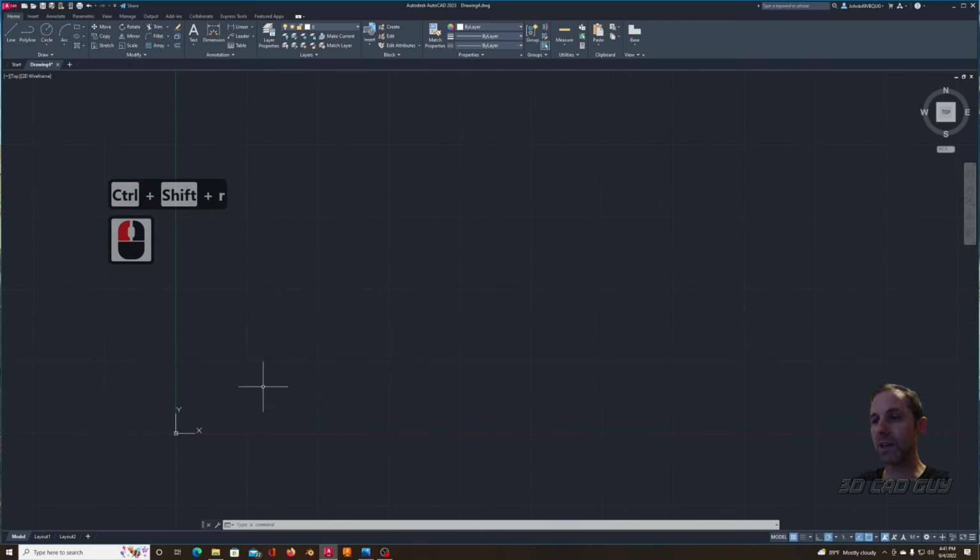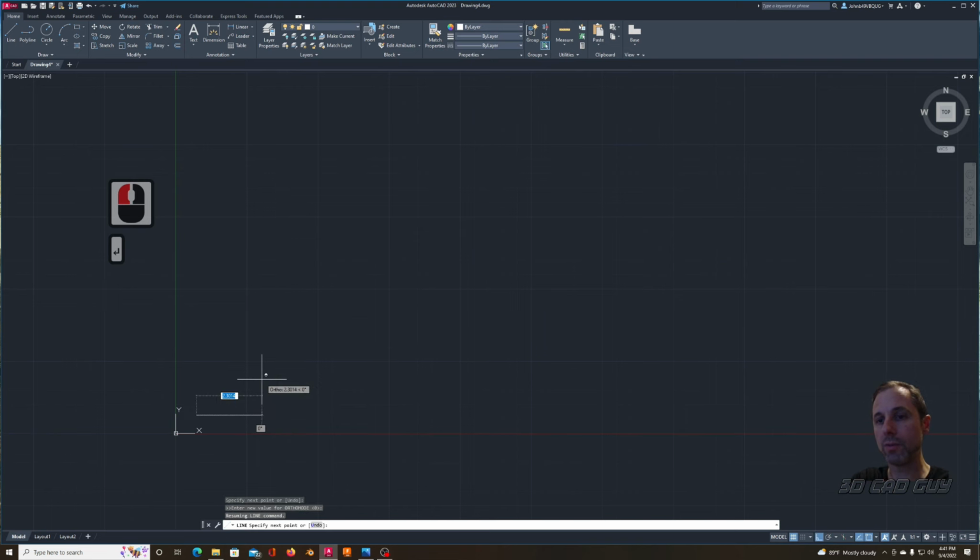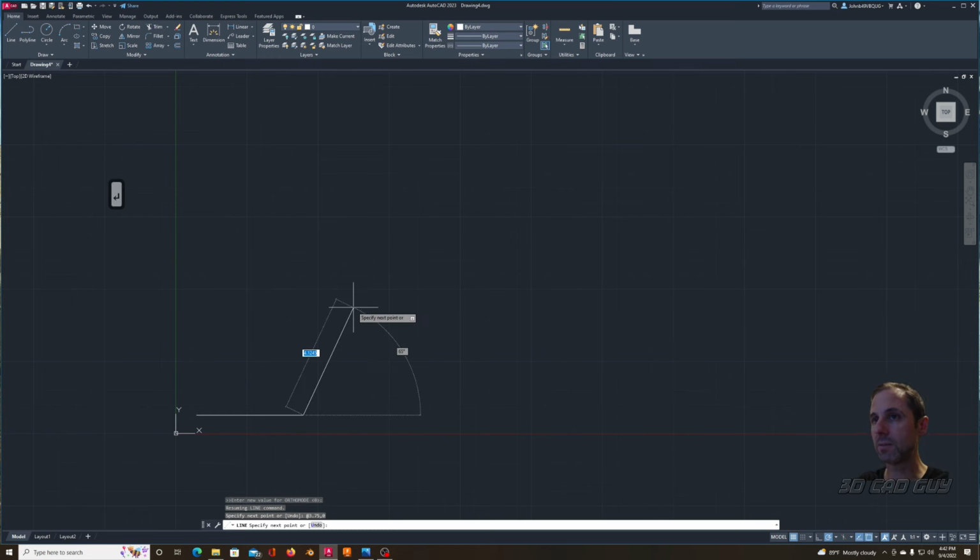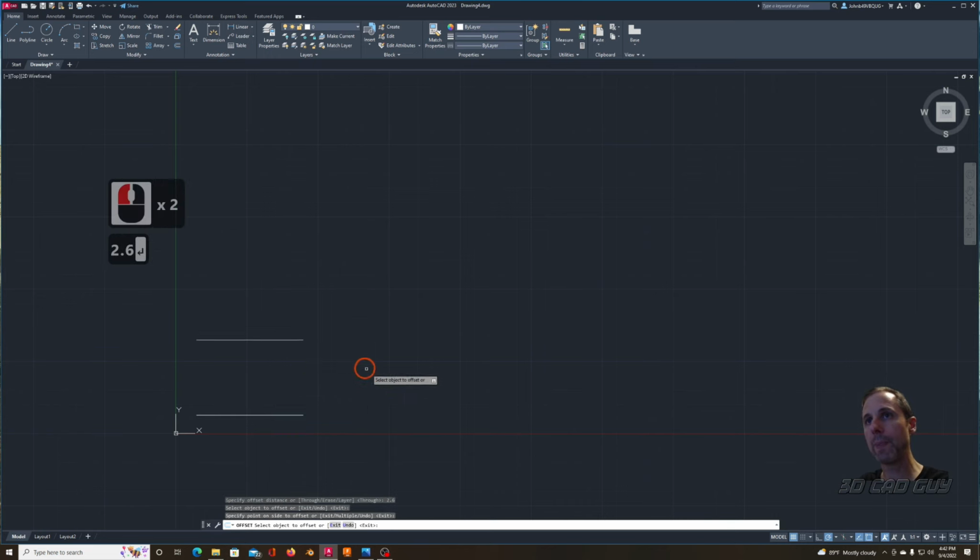All right, we're going to start out with a line command. Click any point. We'll go from 3.75, 0 in y, that's the point over to x, 0 in y. It's your y and your x. Creates a segment. Return again to close it. You just have the one segment. Now we're going to go up to the bottom of the bore, so we're going to simply offset this up. It's going to be 2.6 inches to the bottom of the bore.